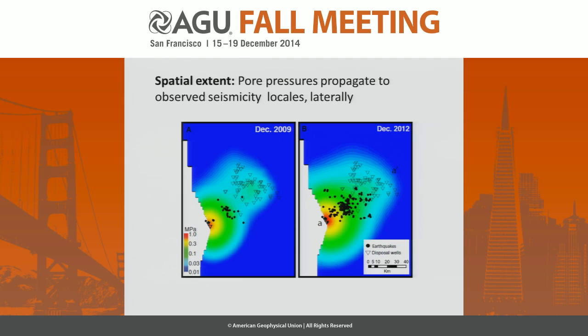And so this is the result of the pore pressure modeling. And here, these two are the plan view. Here's the Nemaha fault. We assume that the other side of the Nemaha fault is not participating in the hydrologic diffusion process. So here are the 4 injection wells at a higher rate.